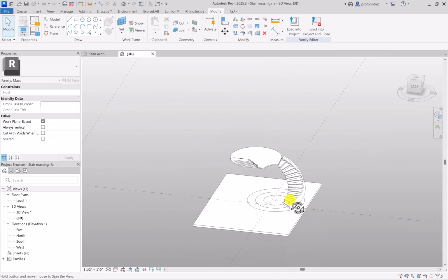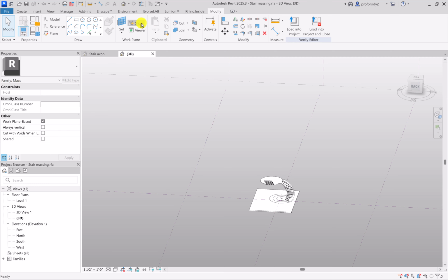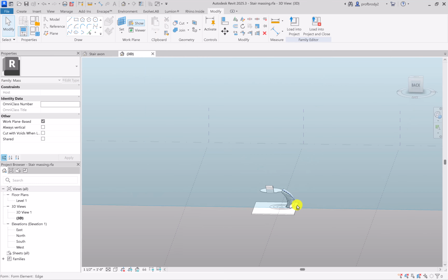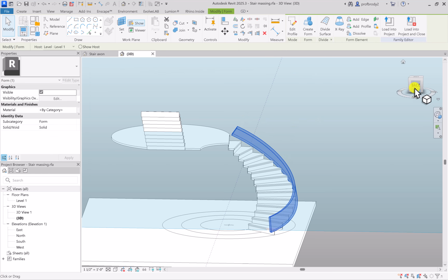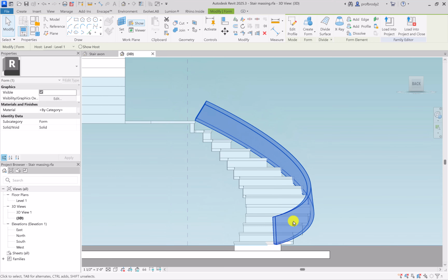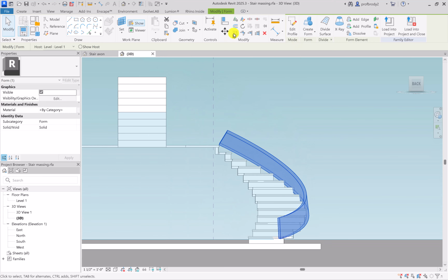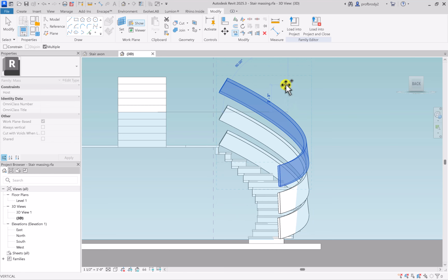Now, one thing that is always tricky is we are in 3D space here. So you make sure that you've set the reference plane to a vertical reference plane. And in fact, I'm just going to show that here. And now I can select this mass like we did before. Maybe I'll even put it in the back view so that I can get kind of a more orthographic view. And let's make a couple copies here. And we'll make a bunch of copies.